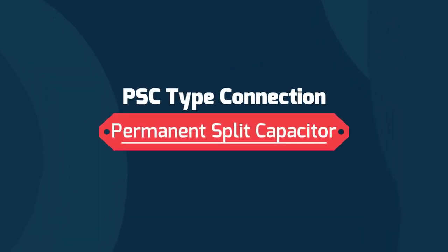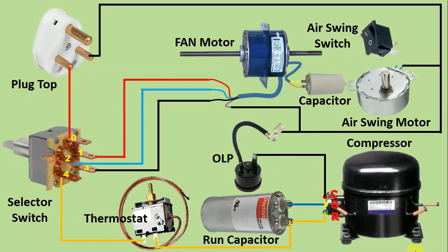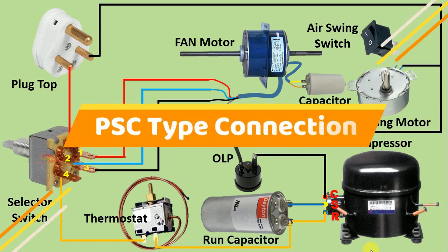Friends, connection of this compressor which I told you, this is of PSC type. PSC means permanent split capacitor. However, we can connect the compressor in many ways like PSC type, CSIR type, in CSR type. I told you connection by PSC type.